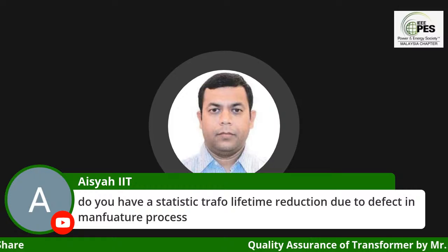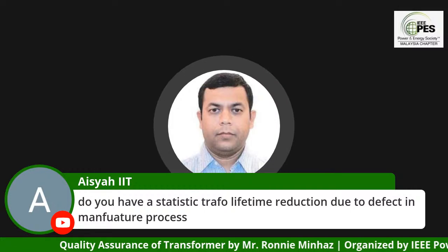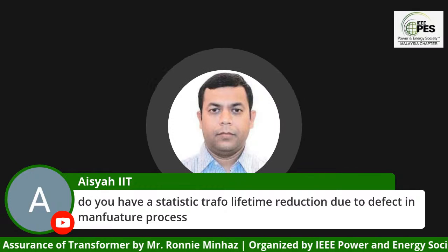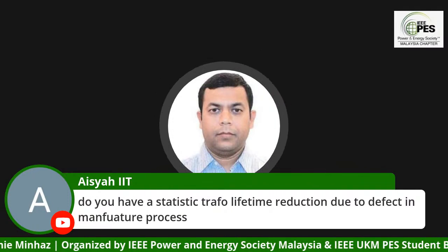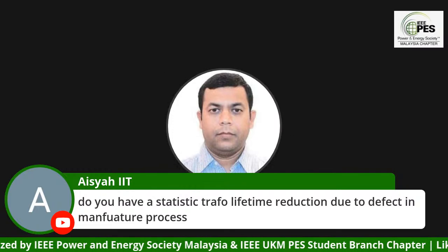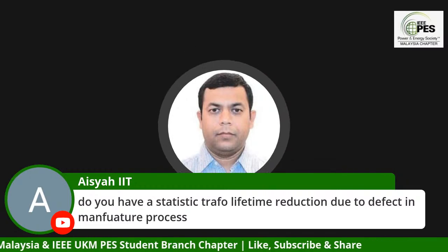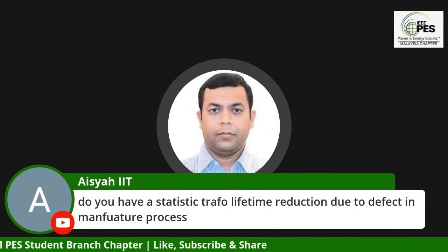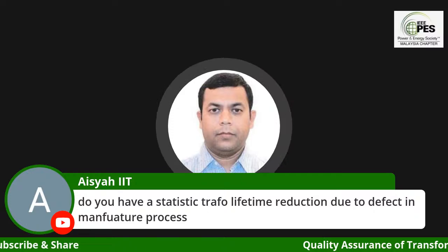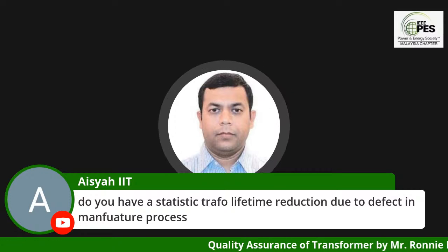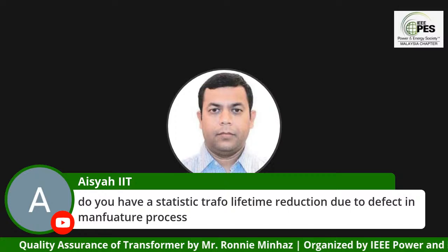But what I can say from my experience working as an equipment engineer in the electric utility, and working as a transformer designer, is that you will not see those things within the first 5 to 10 years of the life of the transformer. Usually the transformer starts to show symptoms after 10 years, depending on how you load the transformer, what your loading process is, and what the environmental conditions are. Let's say, for example, what your ambient temperature is and all those things.